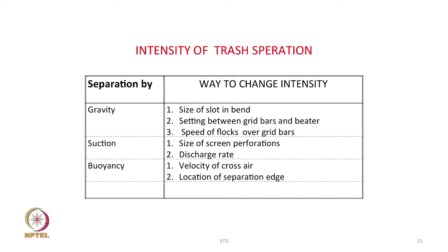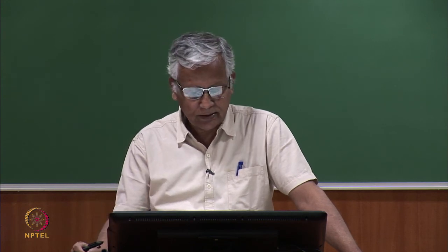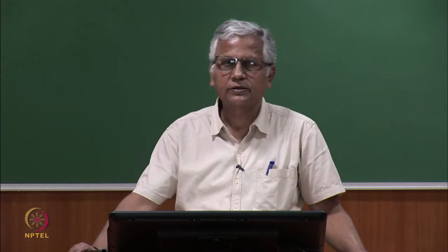The other thing is the suction rate, and the size of the screen perforations. Where we are using a perforated screen or a perforated drum, the size of these perforations will also matter. The other thing is the discharge rate, that is the rate of suction through this suction drum.